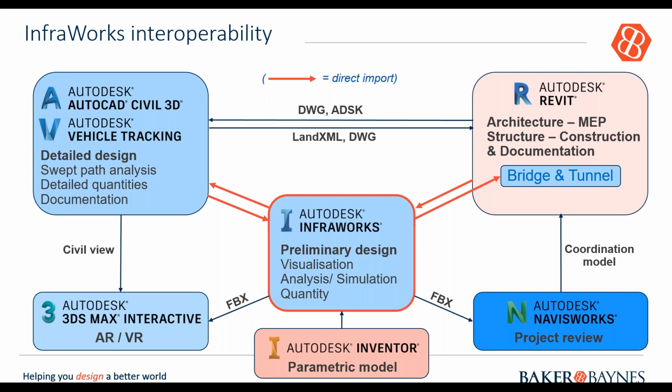If you haven't heard of Navisworks, it's a clash detection tool, very successful in project management. It picks up clashes and it does 4D simulation of your construction. So it's a very good tool used for pipes, for rebar, for modeling, for roads, anything that you can feed into Navisworks, and it can pick up if there's a clash or any interference before you do construction.